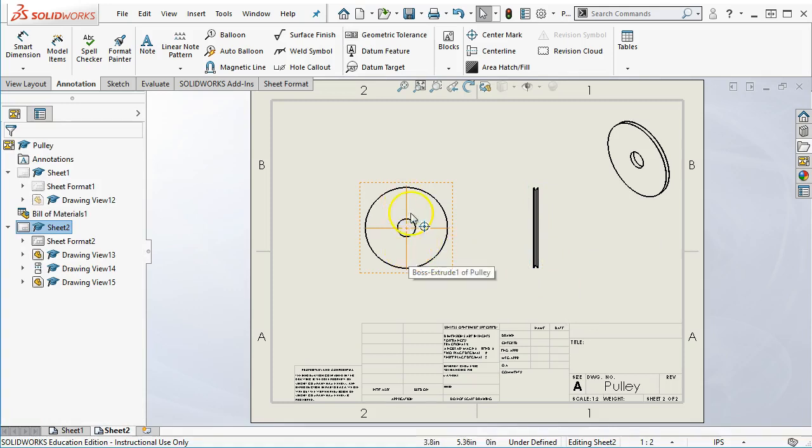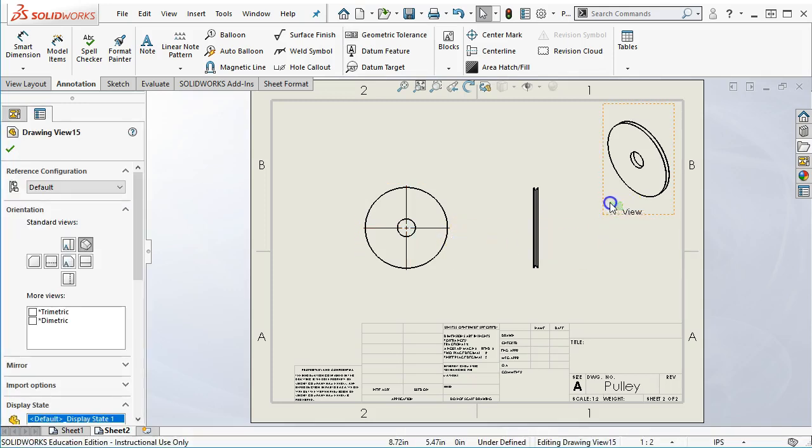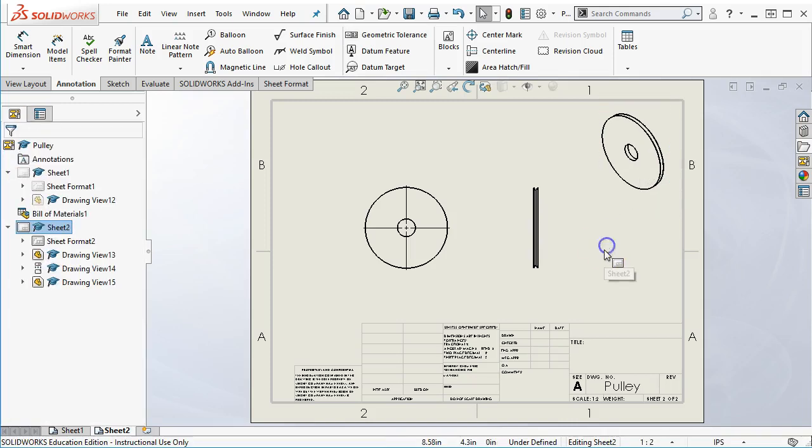It also created the center marks, and again, I don't want to get too far on the drafting. We've kind of taken it this far. It's hard not to go ahead and create this as a working document. So at this stage, we would create layer, and we would also create a dimension layer so we have that contrast and readability built into the document.